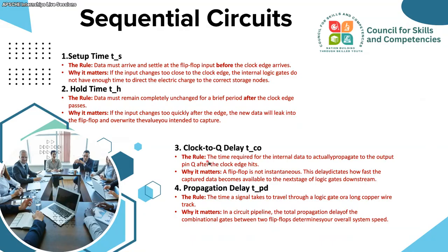Then the time required for internal data to actually propagate to the output of the Q pin after the clock edge hits. So that means the flip-flop is not instantaneous. This delay dictates how fast the captured data becomes available to the next stage of the logic gate downstream.